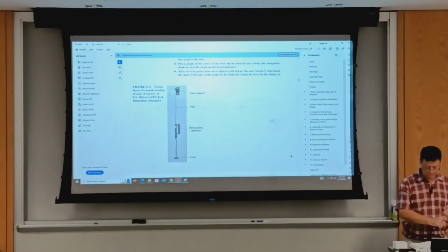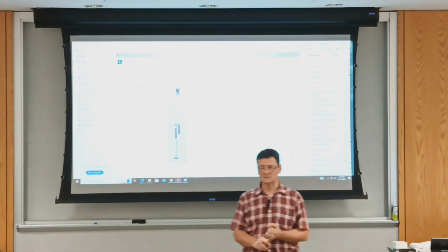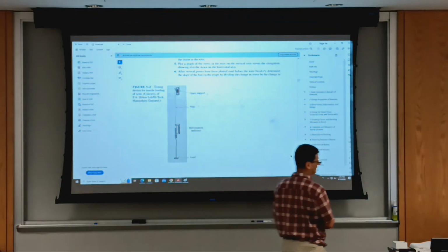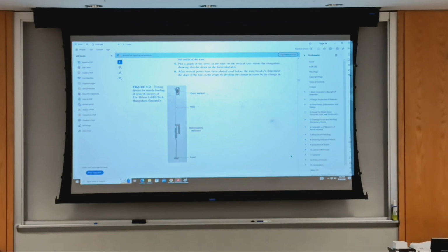You calculate an actual stress, which is a design stress, and how do you relate it to the properties of the material to report the design factor, or maybe calculate the required cross section, or choose the type of structural steel, say, or section for an application.